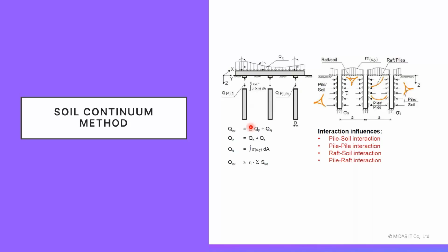If we consider this system in the substructure method, wherein the soil is modeled as springs, we are not considering the pile-pile effect. That means the pile group effect is neglected. The soil continuum method is able to consider the pile group effect as well. Hence this method is very helpful in terms of detailed analysis. We'll see what procedures we have in the soil continuum method. Okay.